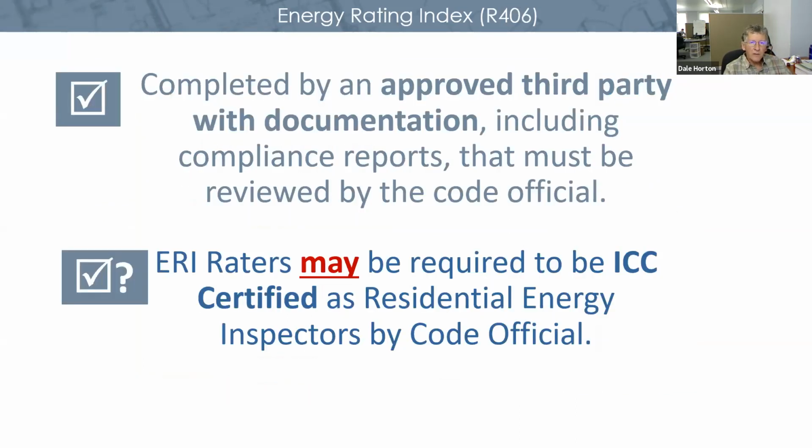So it's completed, the ERI analysis to be completed by a third party, and their documentation and compliance reports must be submitted to and reviewed by a code official. The way it was envisioned that an ERI would work is that the home energy rater would conduct the computer analysis, and then actually inspect the building to make sure it meets not only the characteristics assumed in the computer modeling, but also the other mandatory requirements of the ICC.